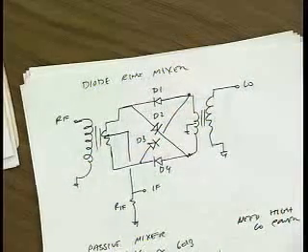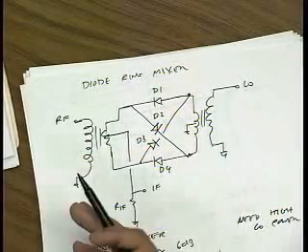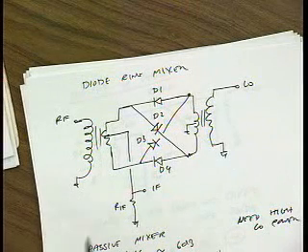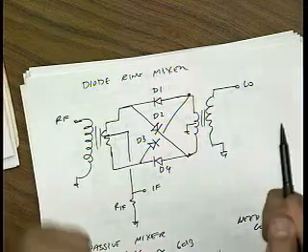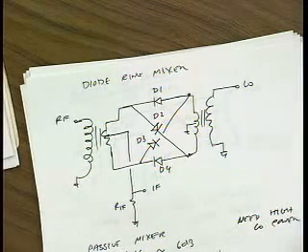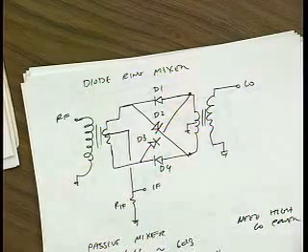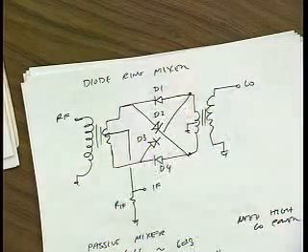Well, what's the equivalent circuit for an ON diode? It's just a resistance, 1 over GM, right? Plus some capacitance, diffusion capacitance. So when it's on, it looks symmetric. Now, you're actually right. If you build these in a real process, then there is a little bit of asymmetry because of the PN junction.